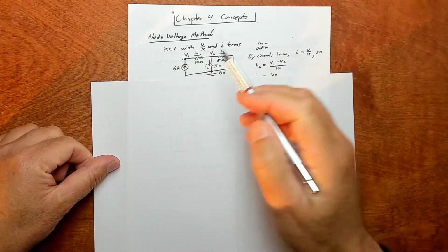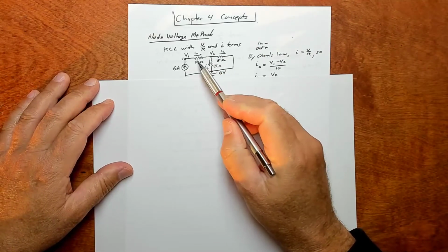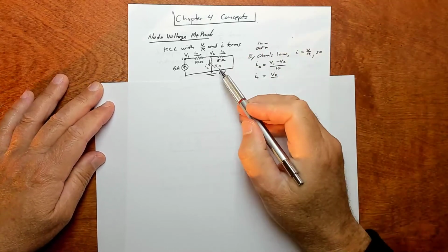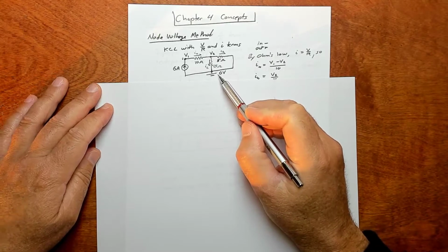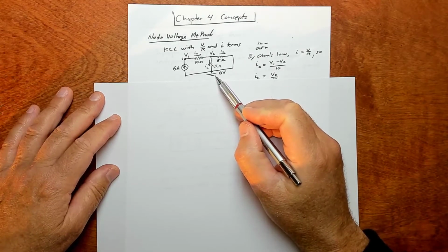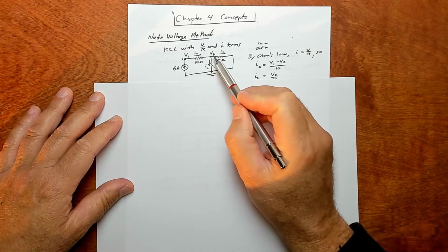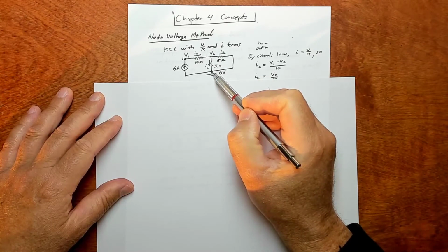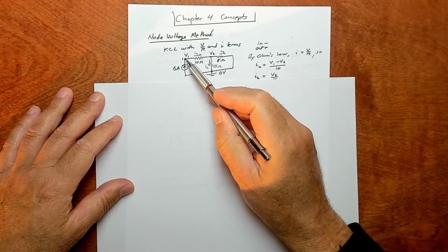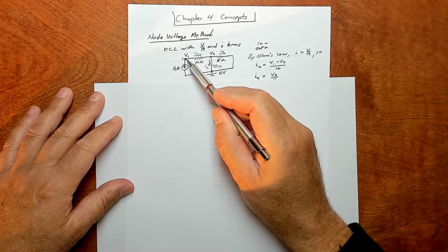So here's a little circuit right here. I've got a 6 amp current source, and I've got these 3 resistors in here. So what you do on these is you pick the bottom node as 0 volts, and that's always going to be the case for us. It's not going to get more complicated than that. So the bottom's 0 volts, and then along the top, between every element, you put a node. So if you start here at 0 volts, then there's an element here, and above that you put this node. Let's call it V1. You could call this node 1. And there's a voltage V1 there.